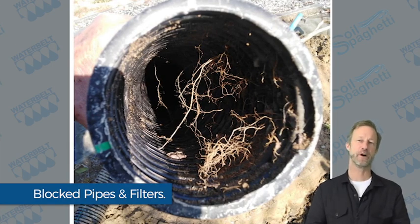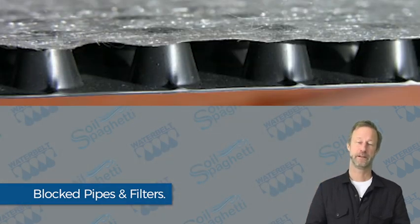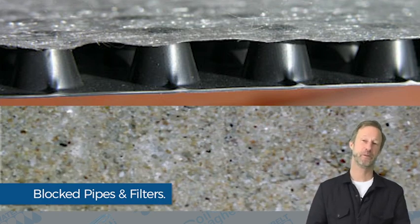Filters are the most recent modification to the perforated pipe drainage system. It's an attempt to block the soil particles before they can travel into the pipe. Filters used for this purpose are geotextile fabric wrapped around the pipe. Filters are just fibers with spaces between them. As the water migrates through the filter, fine particles will be trapped in the spaces between the filaments. Eventually, those trapped particles accumulate and block the filter.